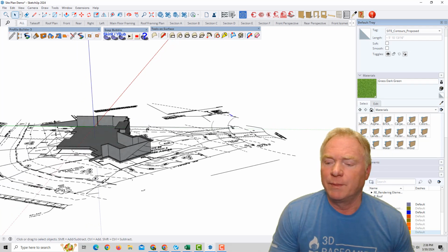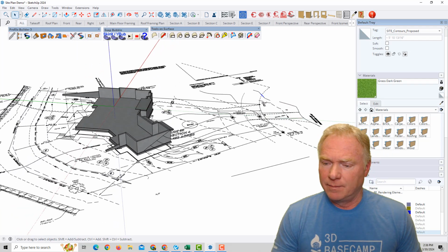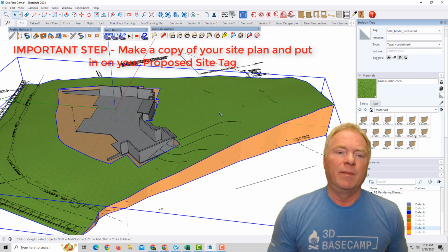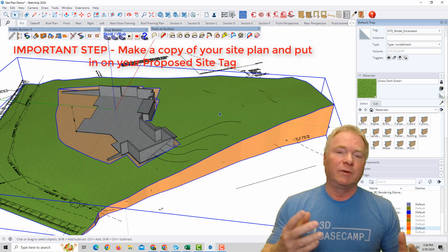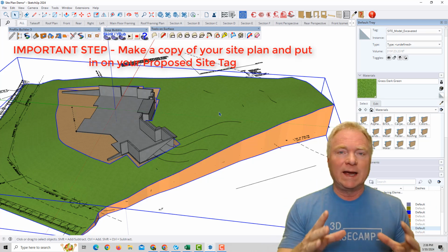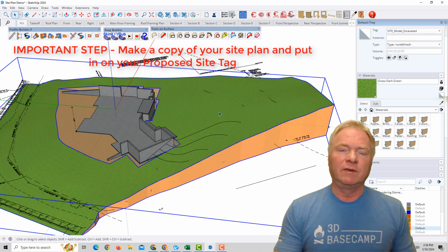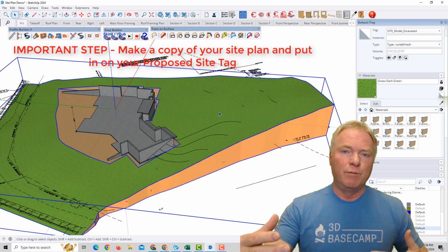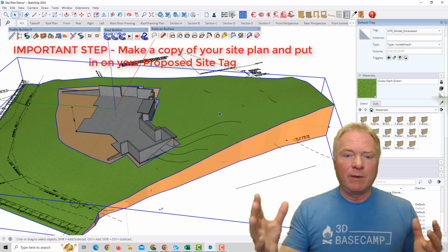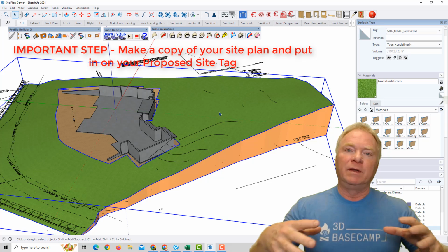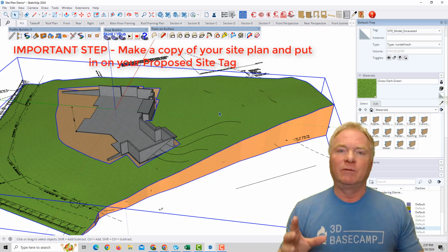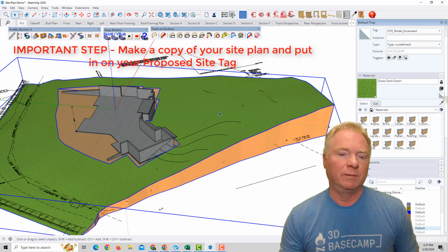All right, so the first thing I'm going to do is take the excavated site model, right? In the first episode, or the third episode, where we did the excavated site, you saw how we took a direct copy of the existing site, and then put it on a layer for the excavated site. Okay, and that way we have 2 copies of it. So we're only going to be destroying the geometry and the mesh on the top of this thing without getting into the sides. Again, it's all about comparing volumes for cut and fill.